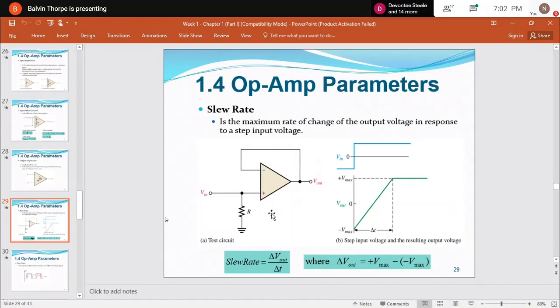In this case in particular, as I said before, because of such a high gain of the amplifier, look at what's happening on the output. The output is this graph, B. The signal will go up to a maximum output voltage and down to a maximum, and up and down again. This is the input and this is the output.